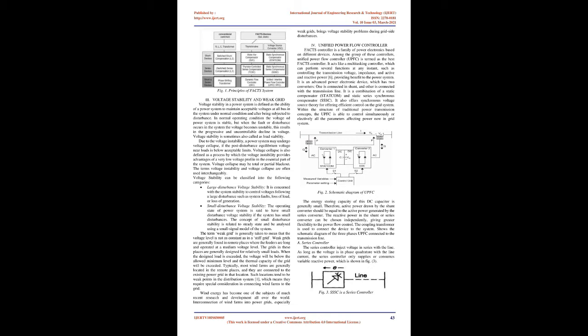Series controllers such as thyristor-controlled series compensator, TCSC, static synchronous series compensator, SSSC, fault current limiter, and thyristor-controlled phase angle regulator, TCPAR or TCPST. Combined series controllers such as interline power flow controller, IPFC. Combined series-shunt controllers such as unified power flow controller, UPFC.